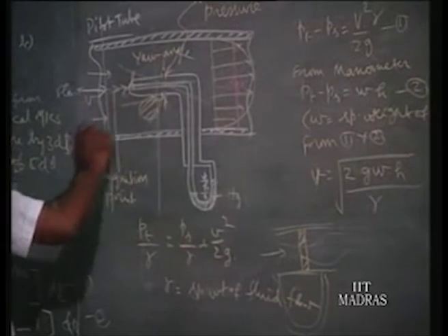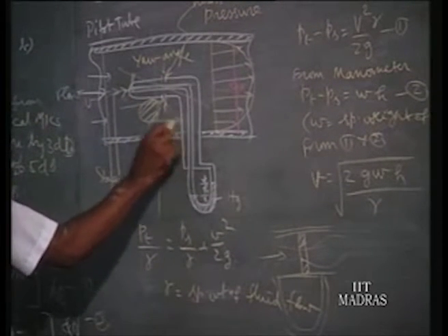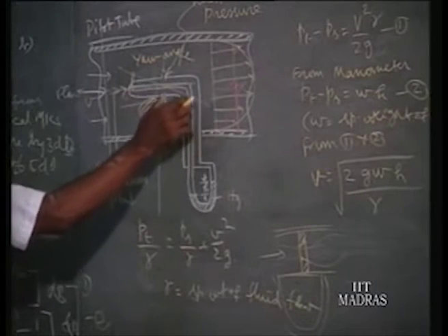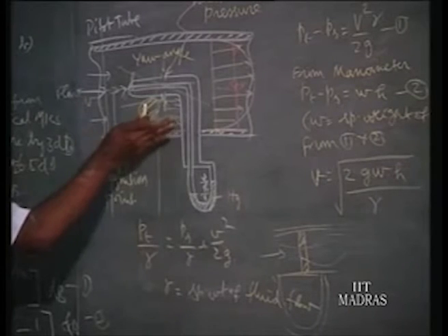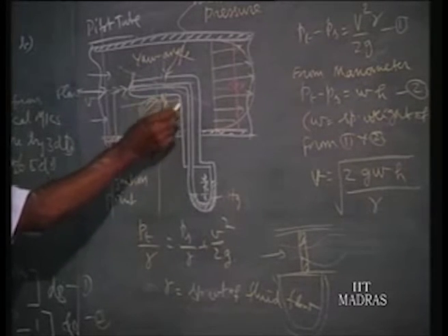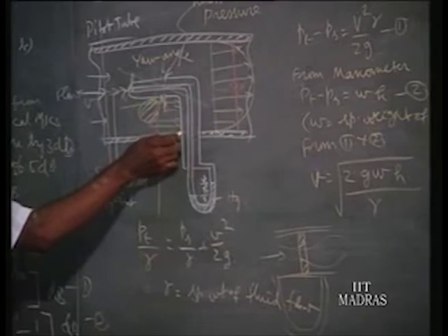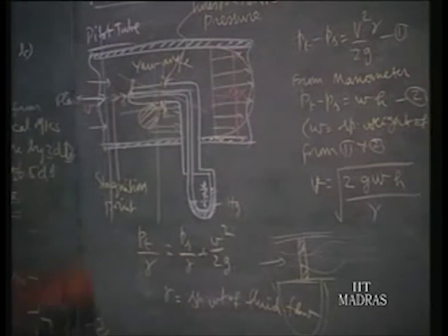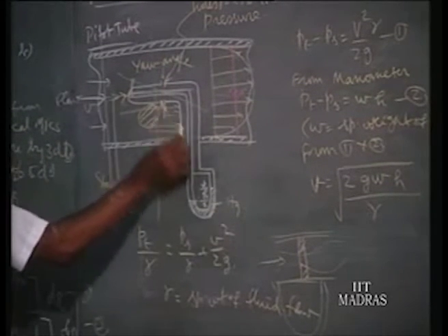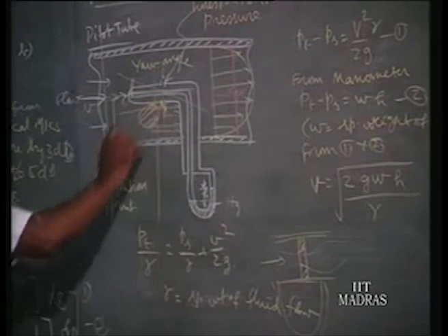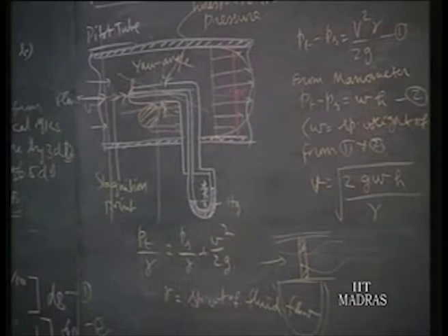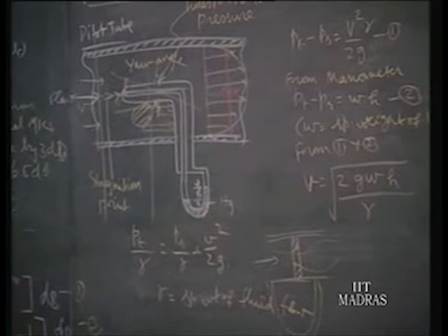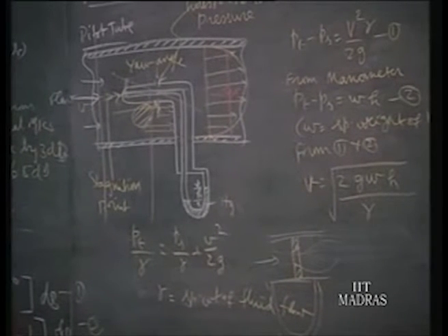So, to avoid it, there is another thing. This is a support side of the pitot tube. It also obstructs the flow. Obstructing the flow means the static pressure increases. By a suitable distance of this limb to the hole, you will find the static pressure drop and the pressure rise can match equally, and then you can nullify that effect. But proper dimensioning is important. That is, this error source can be accommodated, can be properly thought out, and then it can be nullified. But these are some of the error sources.